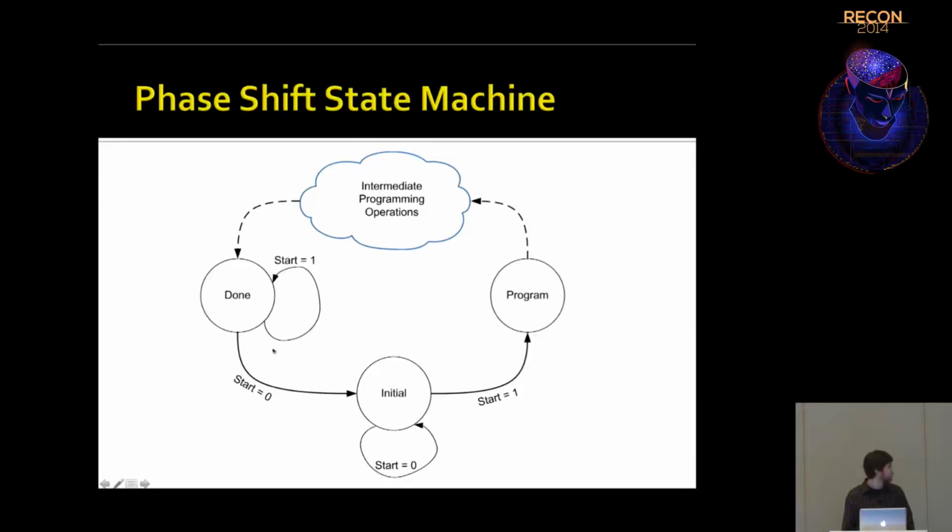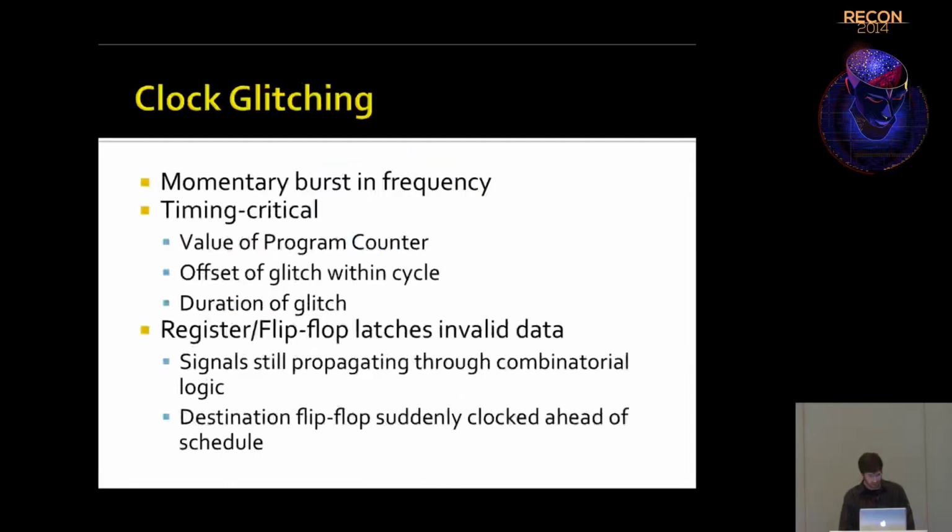It'll just sit there looping, so it won't suddenly fire off another phase shift loop, because otherwise it may be non-deterministic how many times it's actually shifting the phase, and at this point I want precision, not, all of a sudden I've got 180, or this time I've got a 270-degree phase shift. I needed to do that to keep the process straightforward.